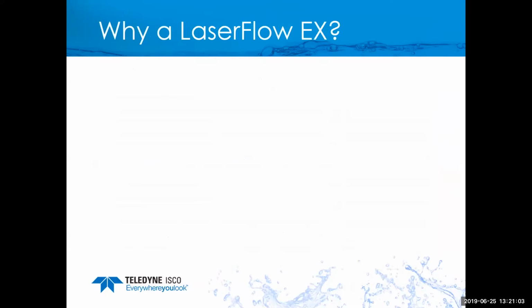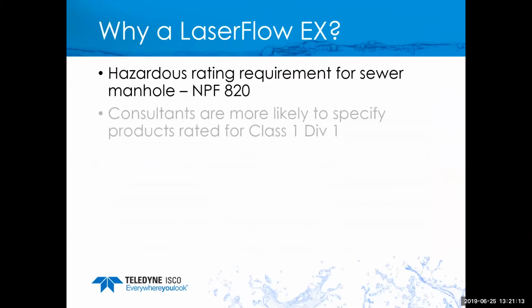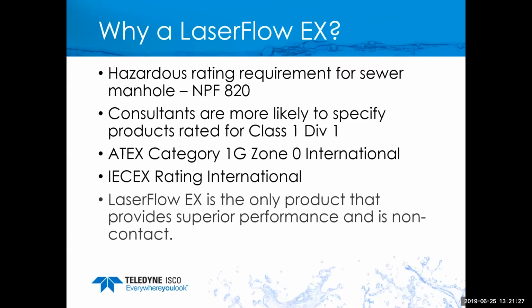All right. So that's how the laser works and the applications that we use them in. But we now have just released one that's called the LaserFlow EX. It's rated for sewer manhole environments, NFPA 820. We have more consultants that are specifying Class 1 Division 1. In Europe, it's ATEX Category 1G Zone 0. IECEx rating, international as well. And LaserFlow is the only one that actually meets all of those requirements for the most part and is a non-contact subsurface velocity measurement.